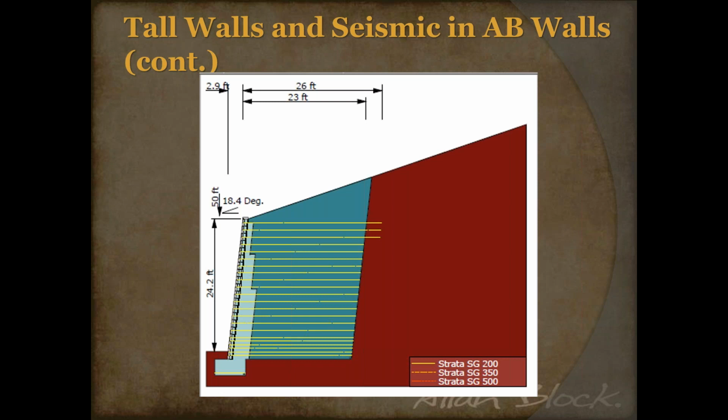well. Because anytime you have extended geogrid or tighter spacing or something like that on a wall design, if it's only in one small spot, it's hard for the contractor to see. It's easy for construction errors to occur. But if someone saw this cross section, it's pretty apparent that it's different at the bottom of the wall than the rest of the wall.